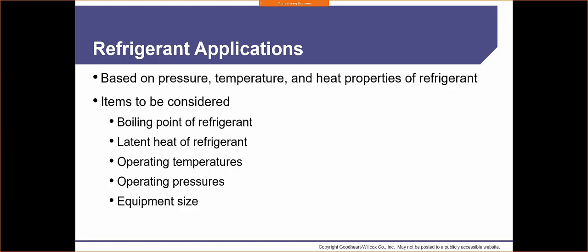All right, there are certain times that you're going to run into equipment that's capable of running 2, 3, 4 different types of refrigerants, and based on the application, you can select what refrigerant is going to work best. But we have to make sure that when we do that, we put in the right metering valve, because that metering valve is going to operate differently on one refrigerant than on another.